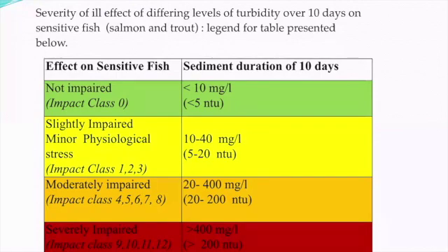Note the severity of ill effects is a local, not cumulative watershed impact assessment. It doesn't have anything to do with overall impact on water within the watershed as a whole. You'd need to come up with an estimate of sediment loading of all disturbed sites upstream of the site, or at least a representative sample of them, to determine the impact on a main channel or intake.